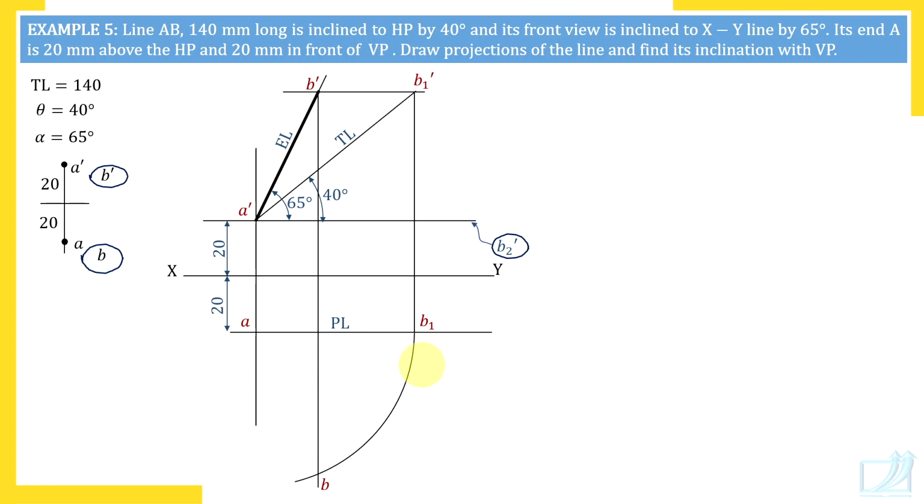Have you realized when you use compass, you get a new point. Now leave the compass. Through the new point, draw horizontal and vertical lines. What I have told you, that unless there are horizontal and vertical lines through all labeled points, you must not use compass. So leave the compass. Through B, now I am going to draw a horizontal line, but join AB, it is the top view of the line. Through B, horizontal line. Which other point is on this line? B2. B and B2 always lie on a horizontal line. So this is the line on which B2 is.